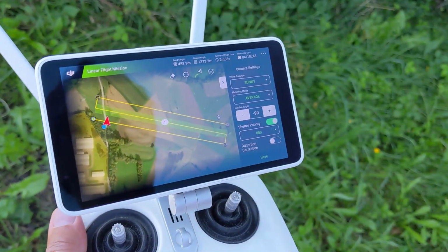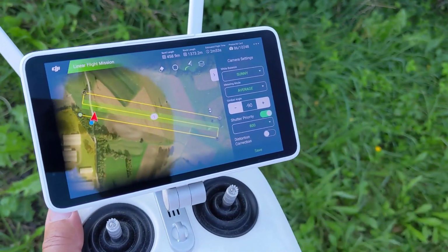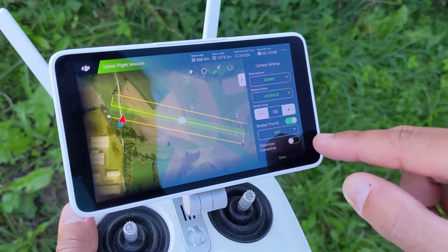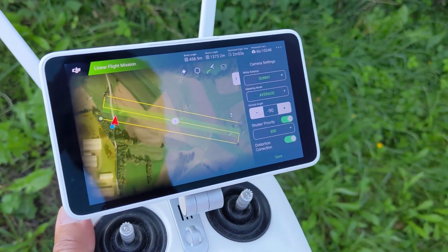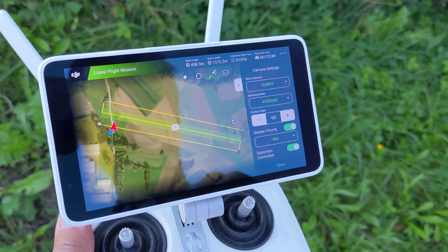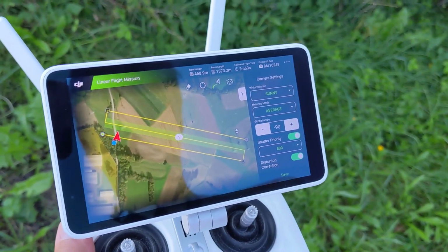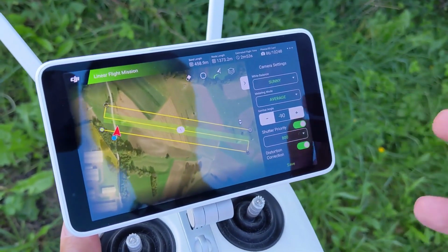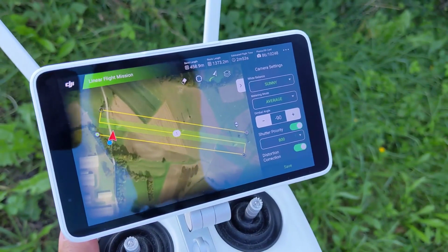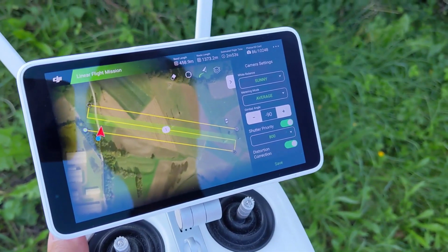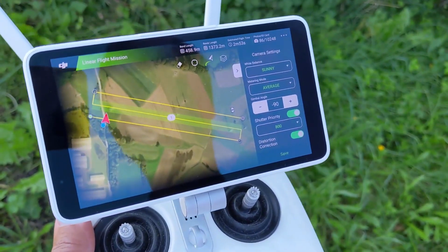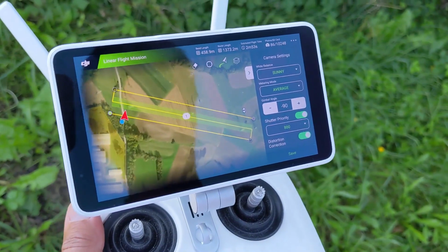So check out this one. And always when you map with a DJI RTK drone, use distortion correction on. This will give you more accurate data, a nicer orthophoto, and faster calculation. In this case the drone is already calculating the first camera distortion based on parameters, and then later in a 3D survey software we do it again, but it's just more effective, everything.